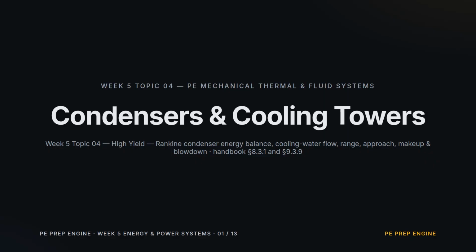Topic 4 of Week 5. Condensers and cooling towers. How a power plant rejects its waste heat, from steam to circulating water to the sky. We close the Rankine cycle in the condenser, size the cooling water flow, then take that heat to a cooling tower and solve for range, approach, makeup, and blowdown.